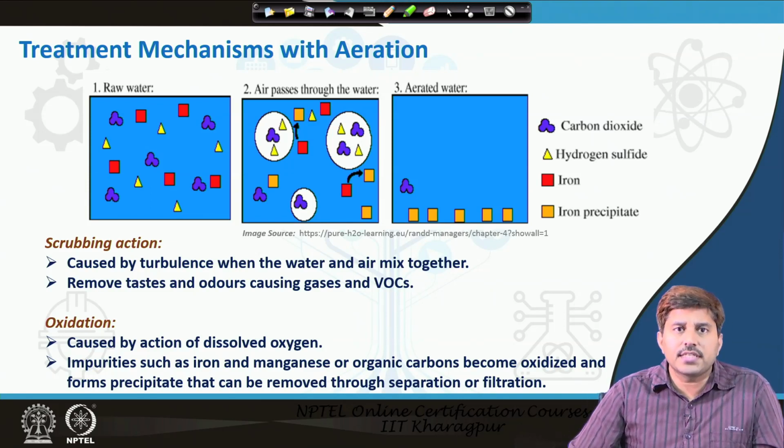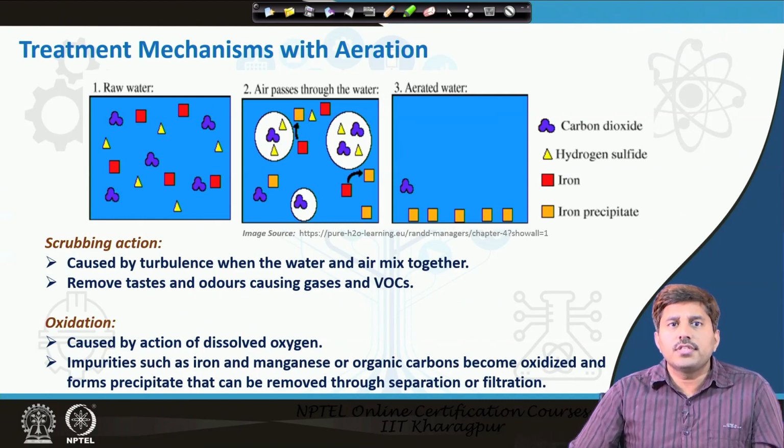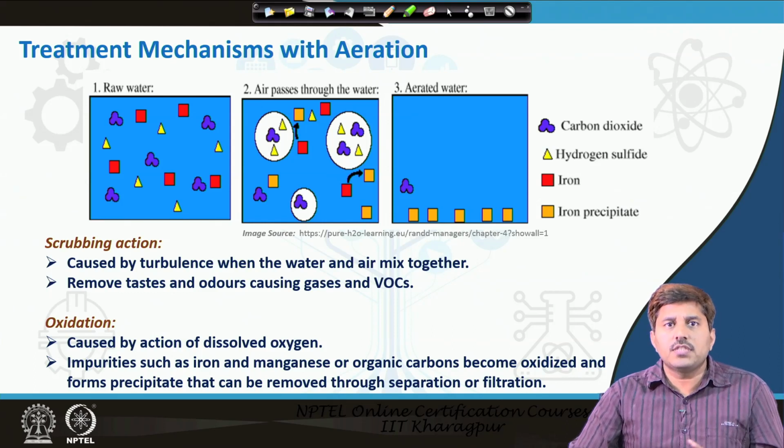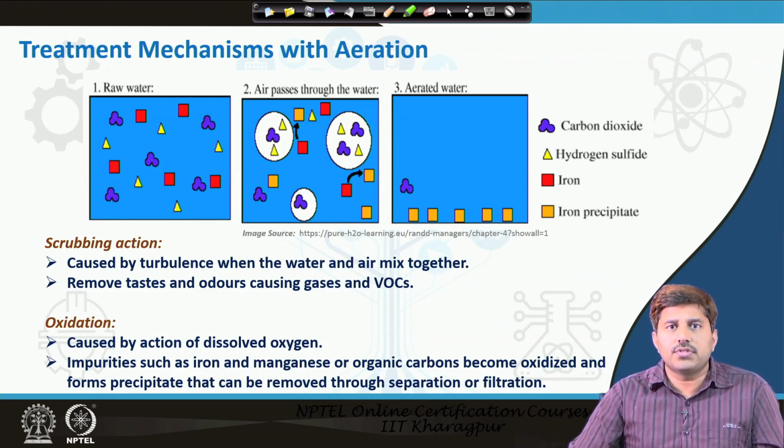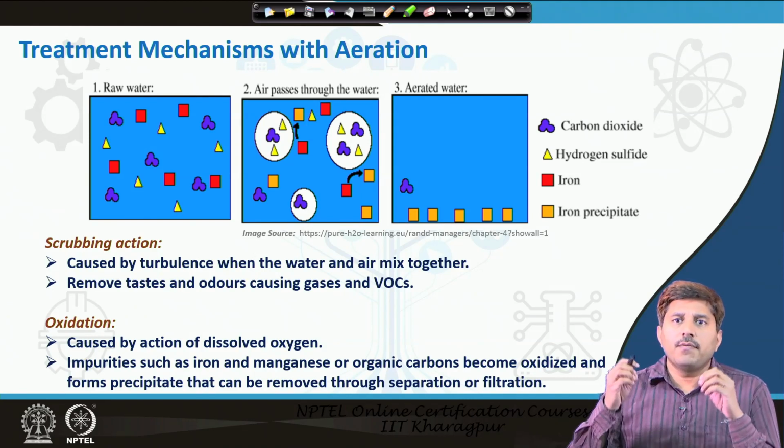One is the scrubbing action, which is because of the turbulence when water and air mix together. So, this removes taste, odors, which are practically caused by the gases and VOCs. Okay. So, scrubbing action is simply like when we are putting air and water into contact, more and more